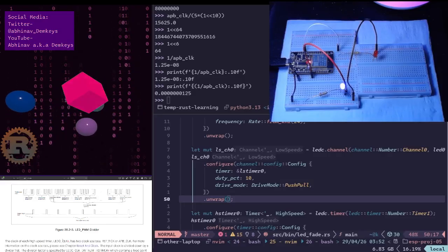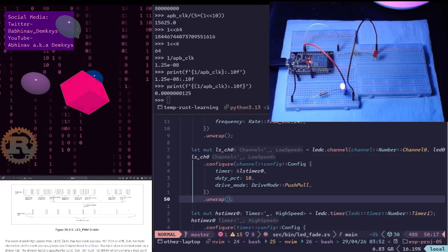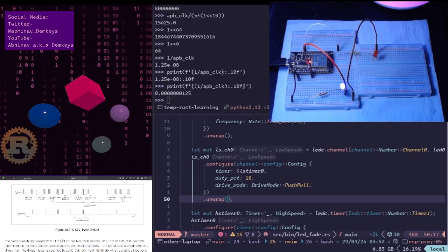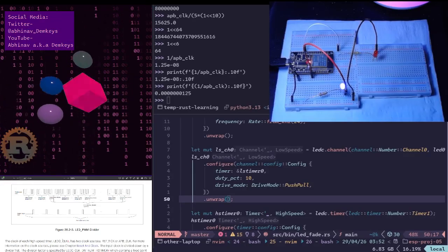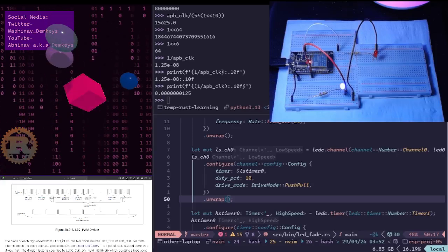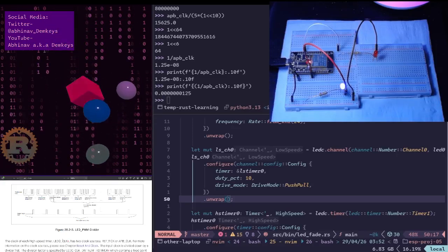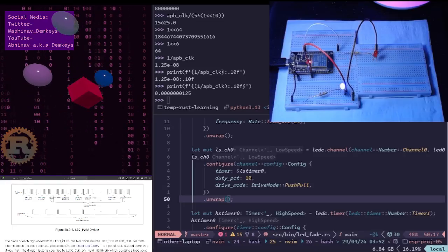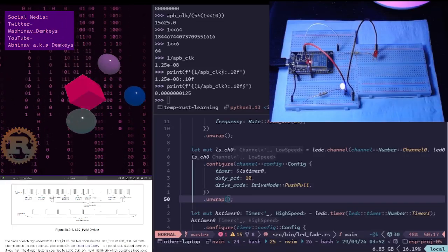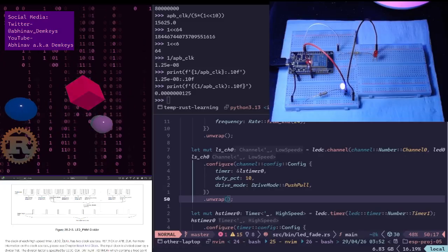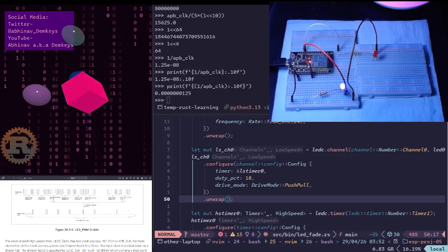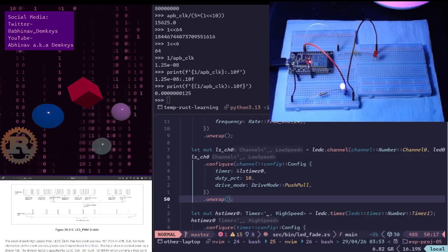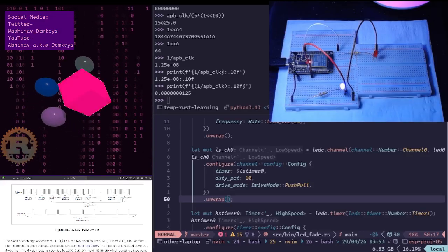If we convert this, it is currently 12.5 nanoseconds. Right now it's being displayed in seconds because we did 1 divided by 80 million. This is how long one tick is. And this is how we give the ESP32 some notion of time. This is how we create the notion of time, and I find that incredibly interesting. We studied this at the beginning when we were learning about ESP32 clock signals and stuff.